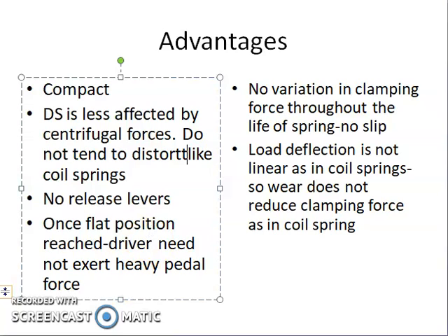Whereas in the coil springs, the driver has to apply more force to press the coil to a larger extent, to compensate for the wear. This will not happen in the case of the diaphragm spring.